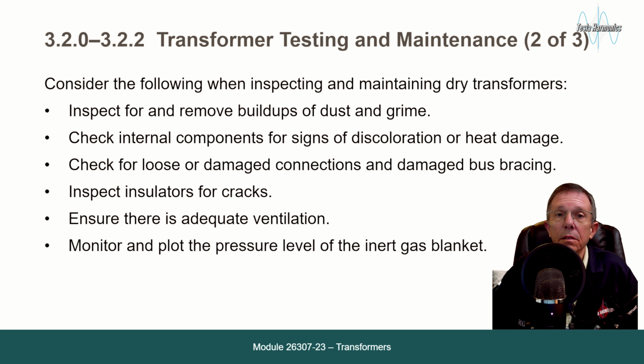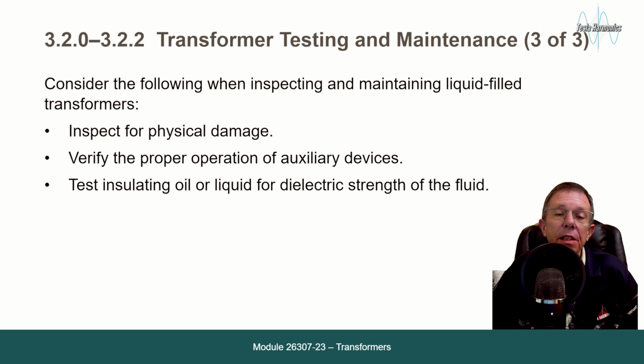gas blanket. Consider the following when inspecting and maintaining liquid-filled transformers. Inspect for physical damage. Verify the proper operation of auxiliary devices. Test insulating oil or liquid for dielectric strength of the fluid.